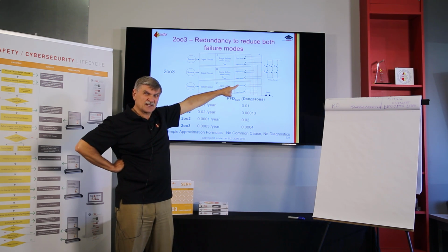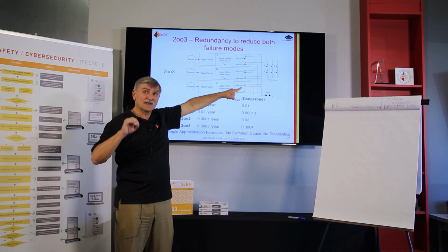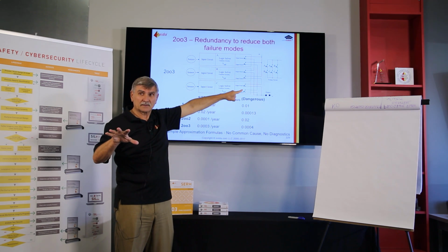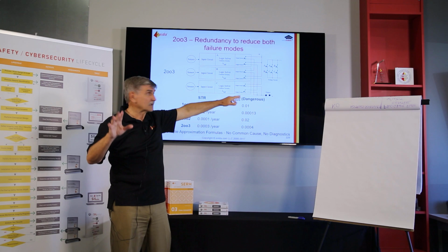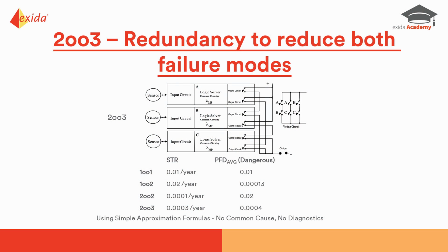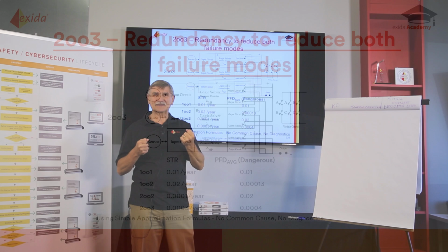Can the set of 6 switches still de-energize the output? Yes, because B and C are still working, and if A is shorted, we can still de-energize, even though one has failed safely.